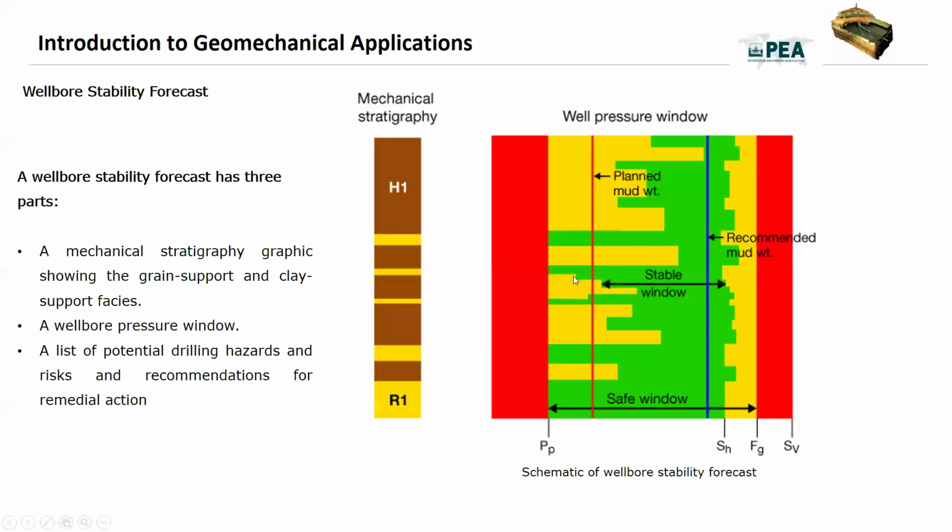If we go down, we have to provide recommended or remedial actions before starting drilling. And also, if we are facing some problems here, for example, we are in this area, we also have to prepare remedial actions. All these things should be known before drilling, and they cannot be known without a comprehensive geomechanical model and knowing all the elastic parameters, the stress limits, the stress, and also the shear failure criterion that will be discussed later. So we have to know all these parameters before drilling our wellbore.